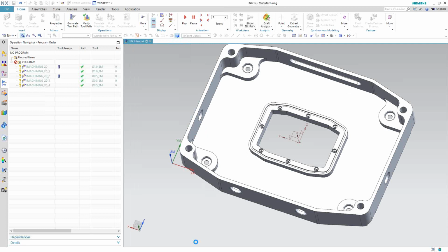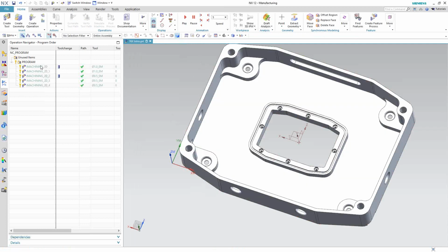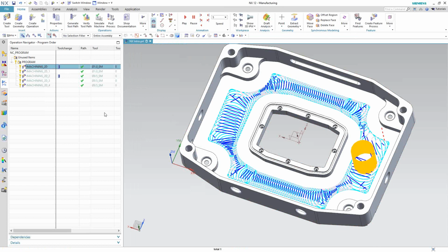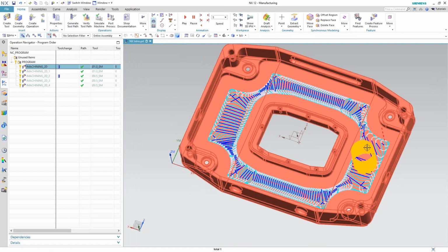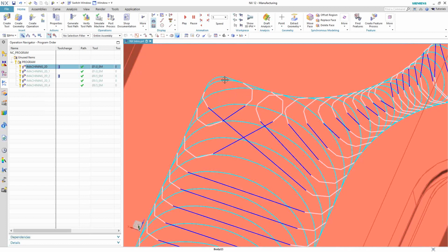Now I'm actually not going to calculate this toolpath because I did previously. So let me just hit cancel, and we'll take a look at the toolpath as it would have been calculated. So as you can see, we've got a little bit of morphing spiral going on here with the entry helix morphing out, some bottlenecks, and some inability to do the morphing spiral here. So it comes out to be a separation channel. All you're seeing here is the separation channel movement.